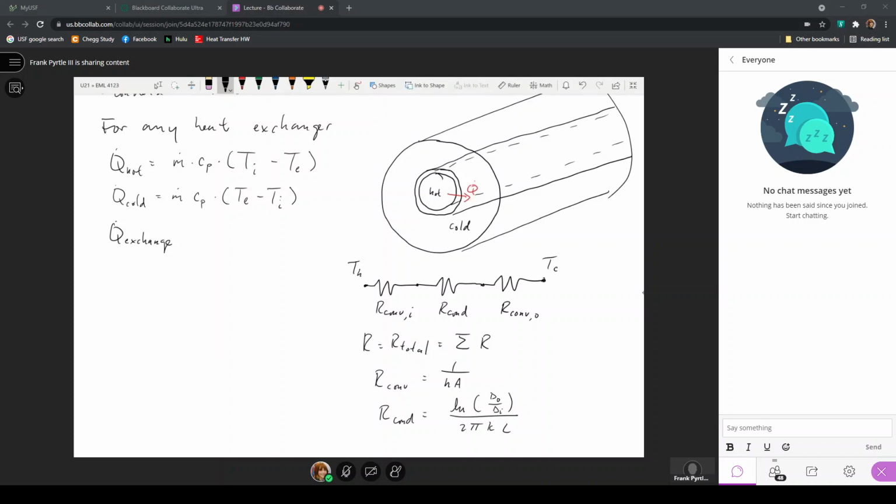But recalling from chapter 8, when we have internal flow in this pipe, as fluid moves through the pipe, if we have a thermally developing condition in a thermal entry region, we know the heat transfer coefficient is changing as a function of position as the fluid moves along the length. Let's say the hot fluid is moving along the length.